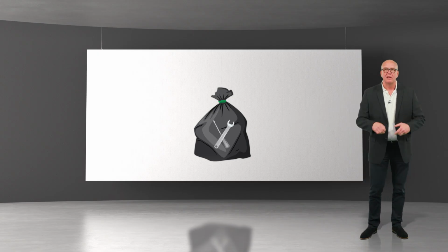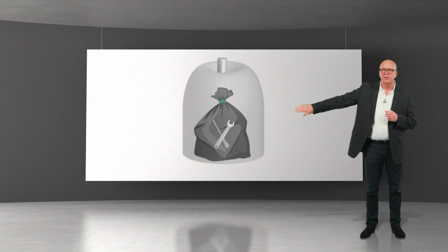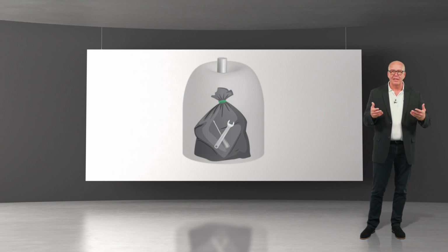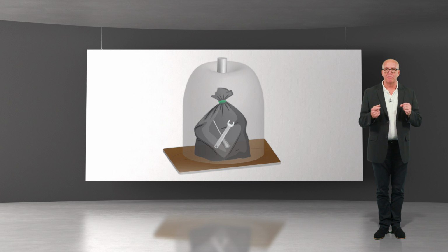The aim of sanitary landfilling is to minimize the environmental impact of waste. In order to protect the environment, 3 barriers must typically be planned. Barrier 1. The waste to be disposed of must be pre-treated and inert. Typically, pre-treatment enormously reduces potential emissions. Barrier 2 consists of technical barriers like bottom liners and capping systems. Barrier 3 is a geological barrier.